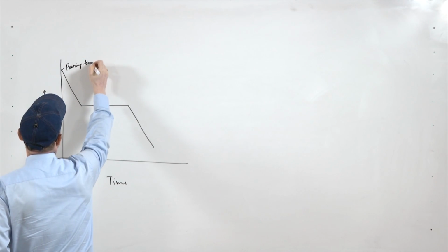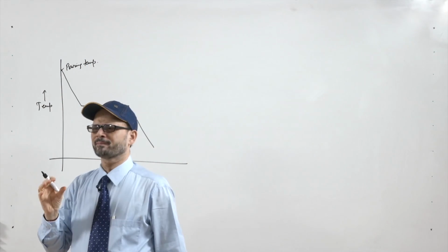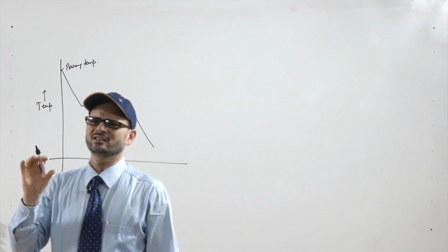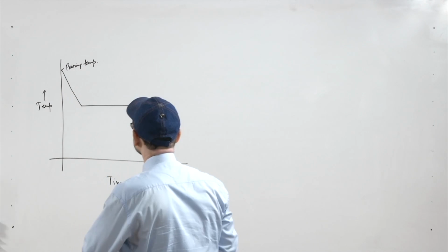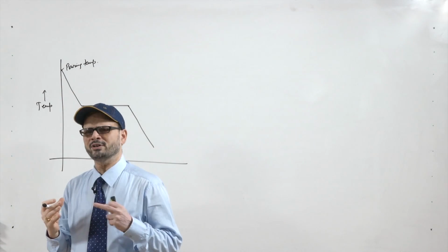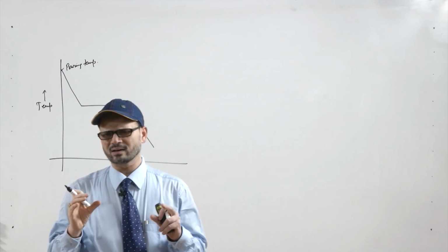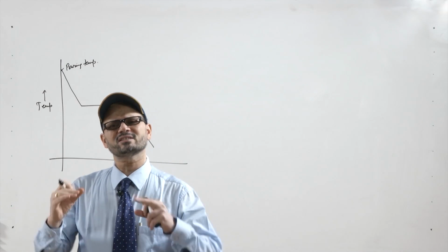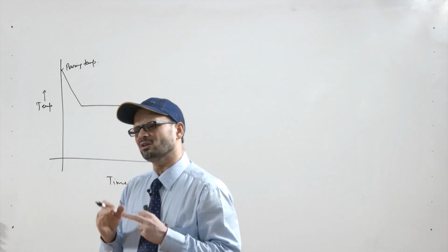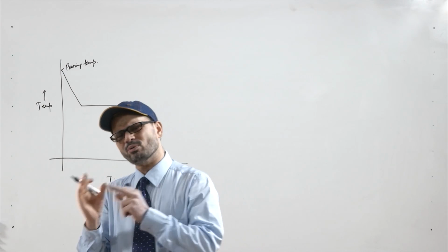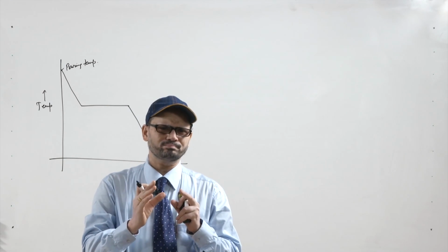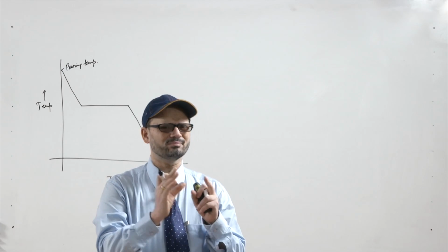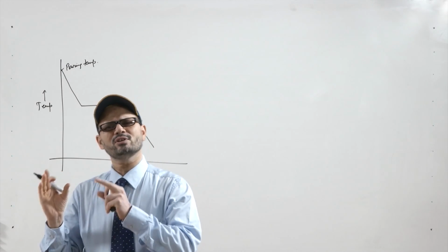Now, at pouring temperature, when you are pouring the molten metal in the cavity, it will start losing its superheat, because pouring is done at a certain temperature higher than the melting temperature of the metal, because the metal has to be transported from the place where it is melted to the place where the mold is placed.